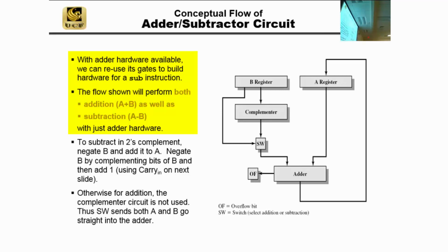This is, I think, very cool, and I always thought this was interesting when I saw it the first time, and I still respect it and think it's very elegant. This box can be any of the adder designs we looked at or other. There are actually many adder designs. I showed you the 3 most popular ones. But now we take an adder and make a subtractor. This is very cool. We use the property that subtraction is the same as adding the negative of the second term. So a minus b is the same as a plus negative b.